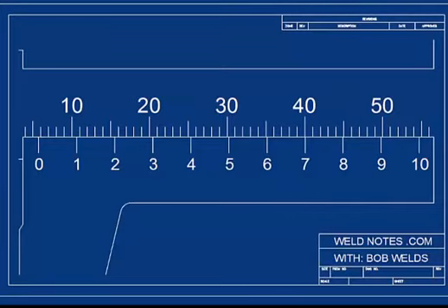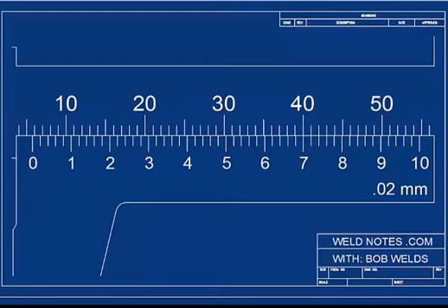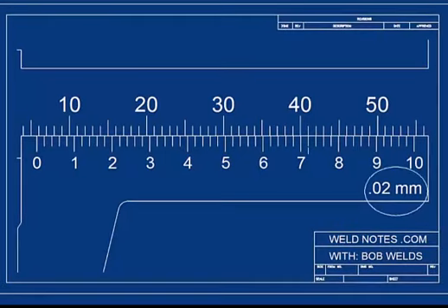But this caliper can measure even more accurately than that. I'll redraw all the marks and let you look again. Now, see that the mark next to the 7 lines up best. But what is the value of that mark? Remember how this caliper had a label that said 0.02 on it? That is what each mark is, 0.02 millimeters.